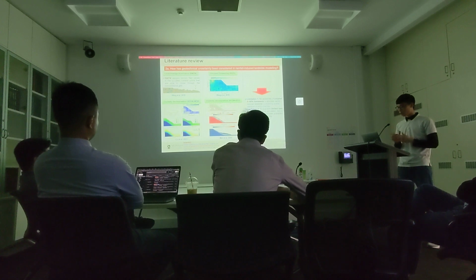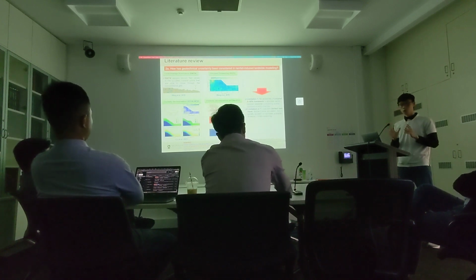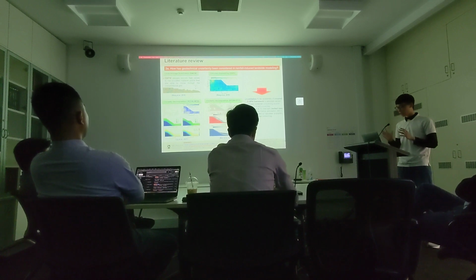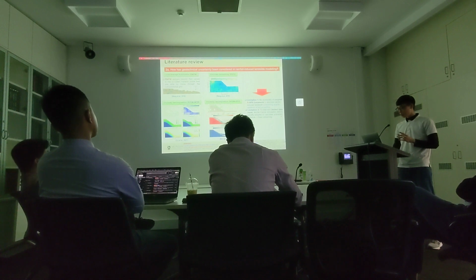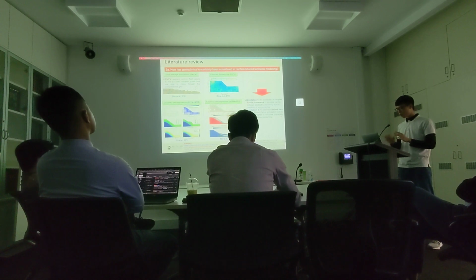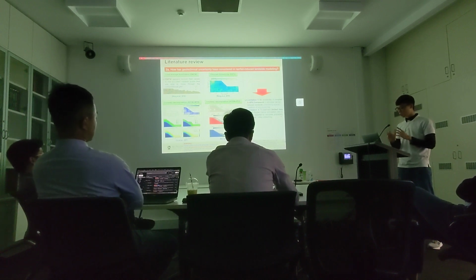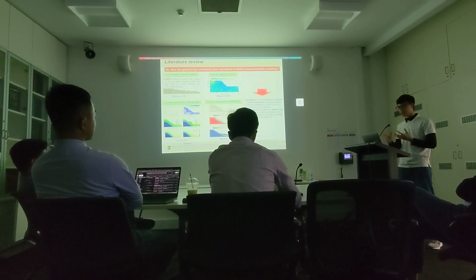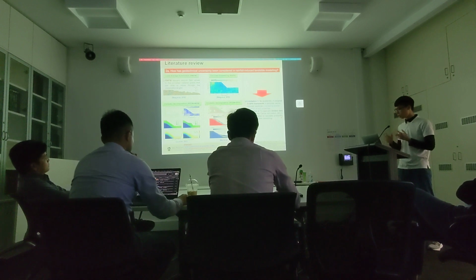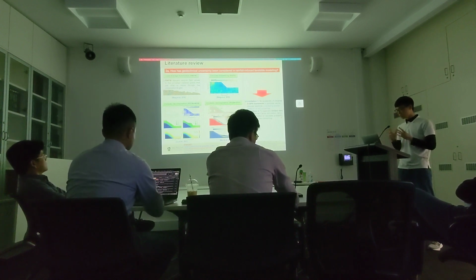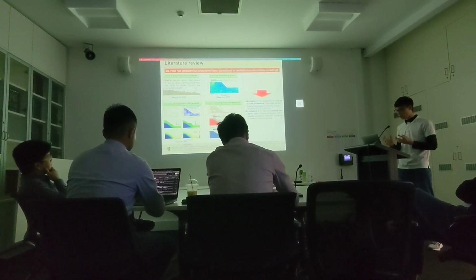The first limitation I want to show here is that the numerical tools we are choosing still lack consideration of the spatial variation of soil properties. The second limitation is addressing the challenge of limited data input. These studies often use Monte Carlo simulation to account for uncertainty by randomizing 1,000 or 10,000 times to calculate the failure probability. However, this approach can be time consuming and does not provide an accurate prediction of time of failure. Therefore, there is a need to find a more efficient and reliable solution.